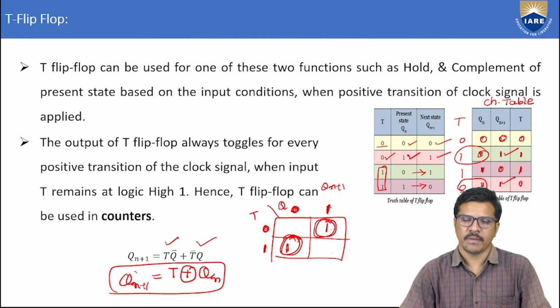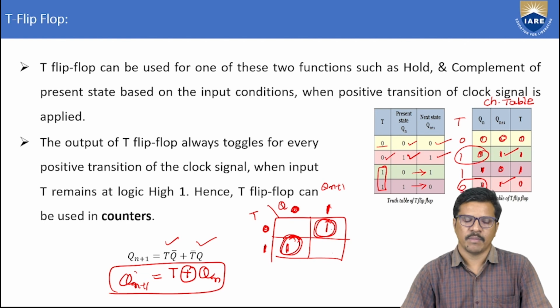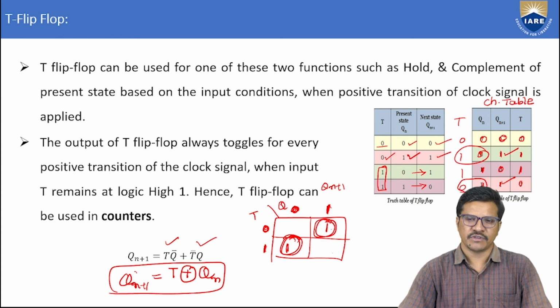But finally, remember that sequential circuits are made with a combinational part plus a memory element, and the basic fundamental component for this memory is the latch. By providing a controllable latch with gated inputs, we get a flip-flop. The basic difference between a latch and a flip-flop is that without a clock it is a latch, and by providing the clock pulse with a gated input, it becomes a flip-flop, which can store the binary information of either 0 or 1.